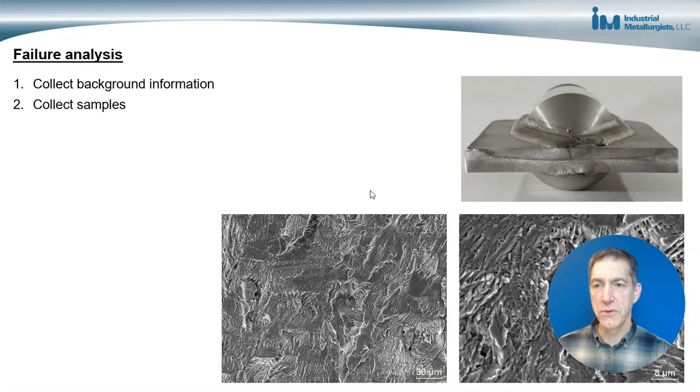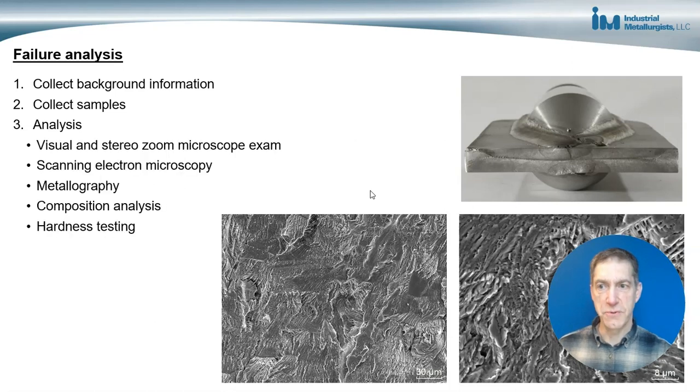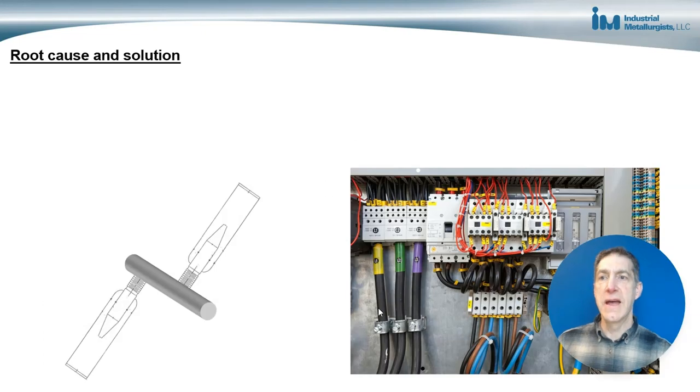Also, we collected samples, and then we had the analysis performed and used visual and stereo zoom. Used a variety of analysis techniques to get the information needed to understand what was happening. And it turned out that the blades were failing due to high cycle fatigue.